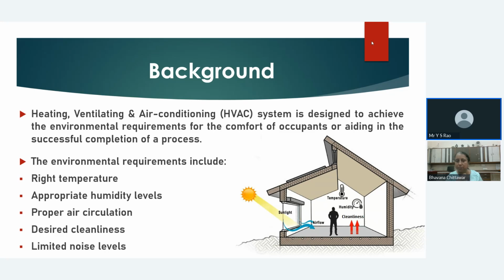And we all know that the main function of an HVAC system in any building is to create a comfortable environment, if it is designed for comfort application. A comfortable environment can be created by maintaining the right temperature, controlling the RH, regulating the airflow, governing the cleanliness, and leveling the noise.